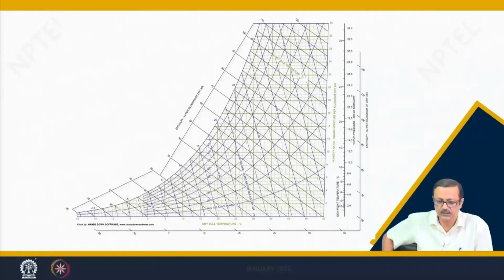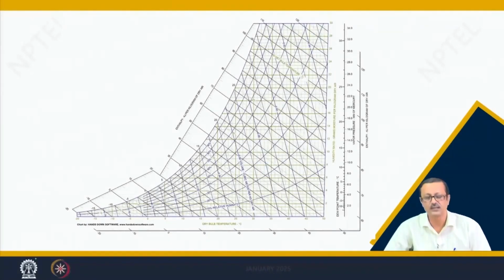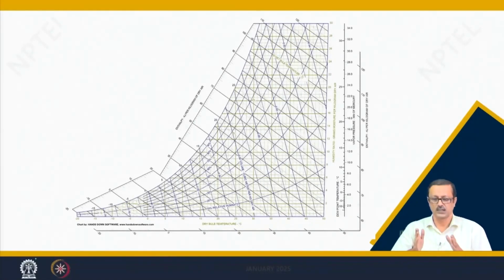We discussed this in the second or third lecture probably, the psychrometric chart. In the psychrometric chart, the x axis is the dry bulb temperature, the y axis is the humidity ratio, and those curved lines are the relative humidity curves. Based on this chart, let us assume a boundary, defined with 2 dry bulb temperature lines and 2 relative humidity curves.